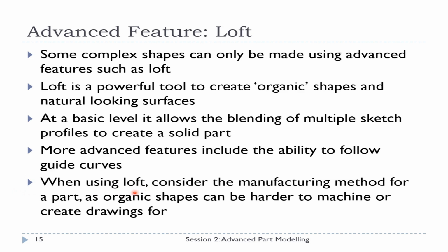So when using loft, consider the manufacturing method for a part. So organic shapes or free-form surfaces are typically harder to machine or create drawings for compared to prismatic geometries.